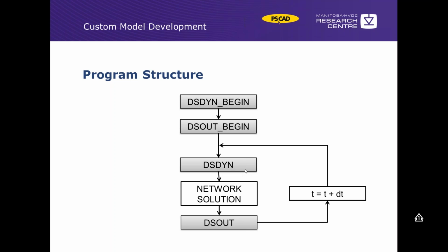DSDYN is called before the network solution. So if you have a piece of component that is going to affect the solution in the current time step, we should have it in the DSDYN, and DSOUT is after the solution.